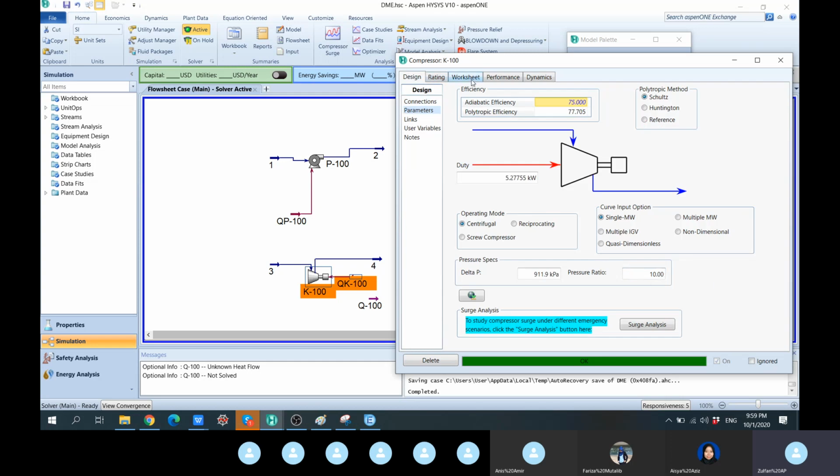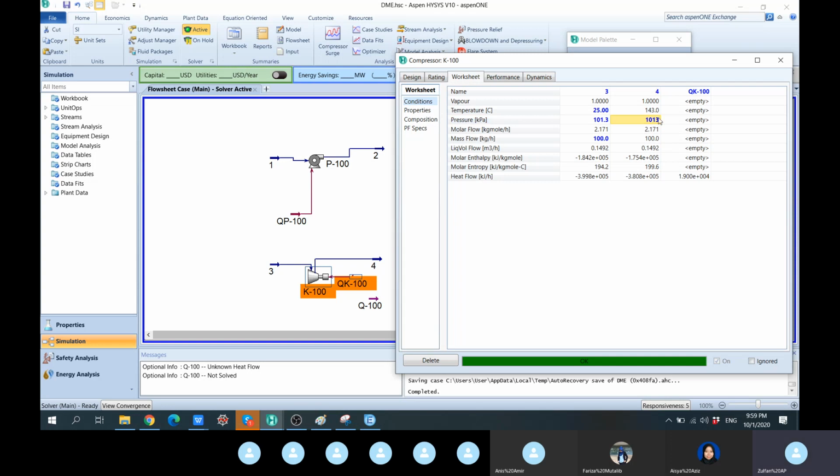So in this case, we have already a compression ratio of 10 times. And then we still don't limit. I mean, now it's 140, 150. So we are already at the typical border of temperature allowance for the compressor. So in this case it's okay, right? You could compress it even to 10 times higher. So you are not limited to this 3 or 4 or whatever nonsense that you are hearing from the outside. The basic is to understand why they put that constraint.